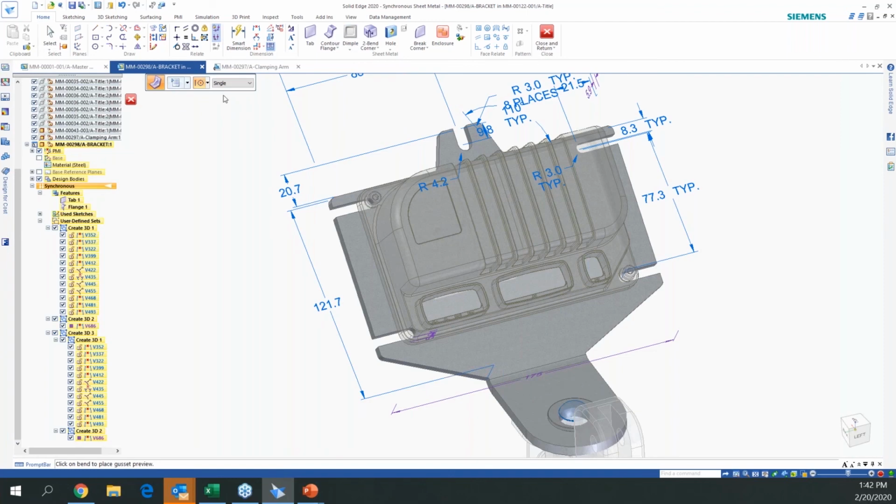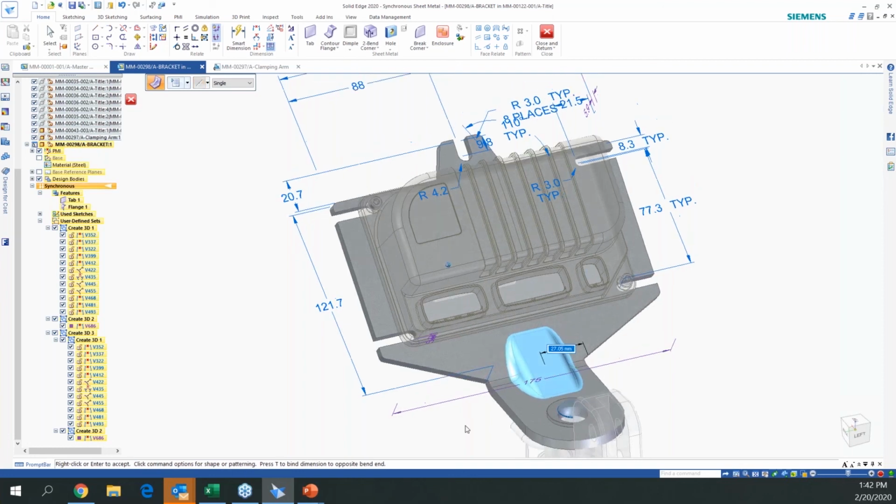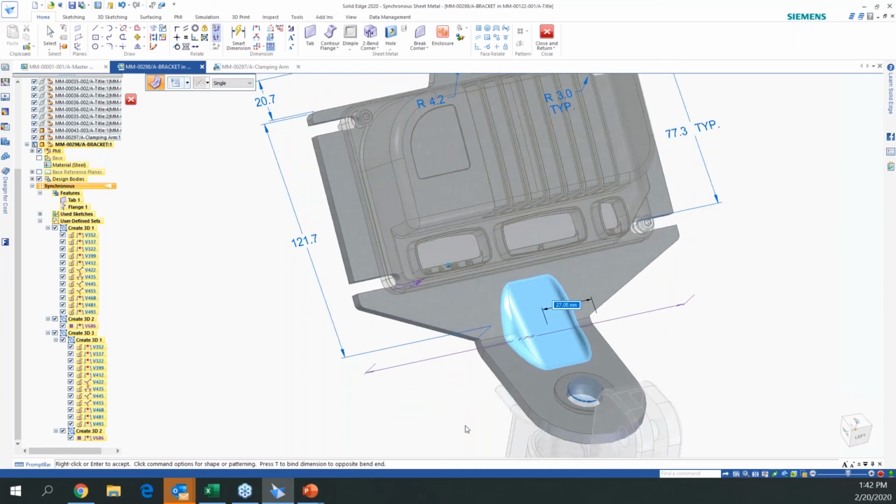So I can be adding a gusset, and I want to add that to my midpoint. I'm going to select the gusset on that radius, but you can see it gives me a preview and I'm not sure exactly where to put it. But remember, I selected that midpoint. So if I move this around a little bit, that midpoint is going to pop up on me. So you can see it pops up. I make my selection on the point.